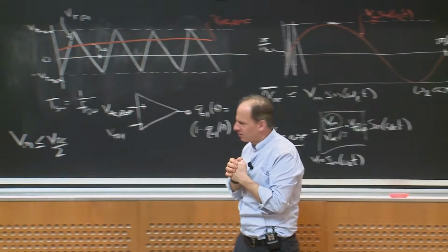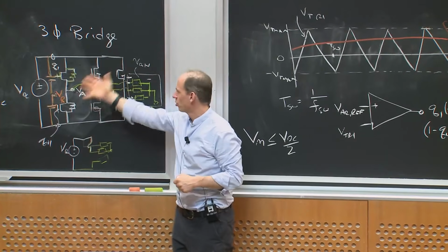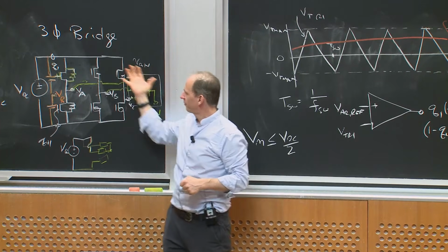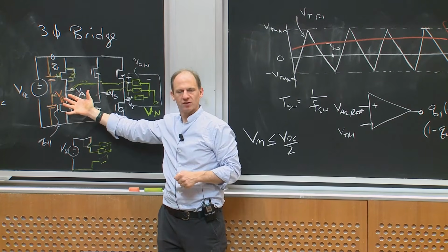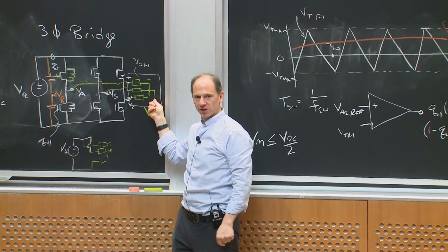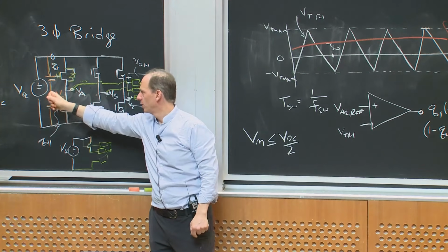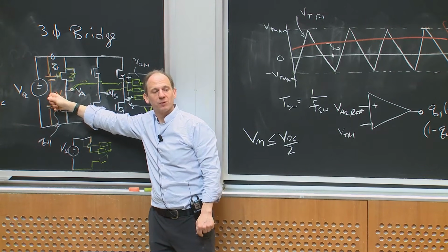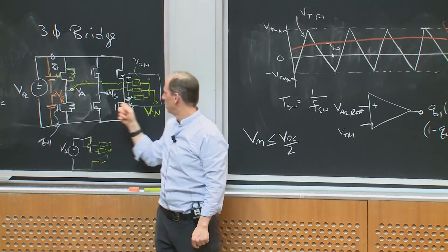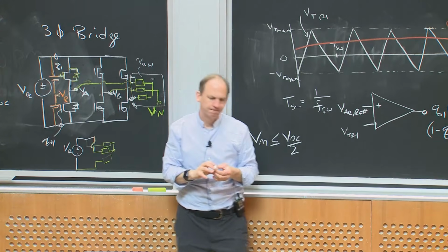Well, that's fine, and through this whole period, at least averaged over a switching cycle, if I'm doing this sinusoidal or sine triangle PWM, this neutral point average over a switching cycle always has 0 average voltage. In other words, equal to the reference voltage, halfway between the bus voltage. So I'm not getting any third harmonic swinging around on the neutral.